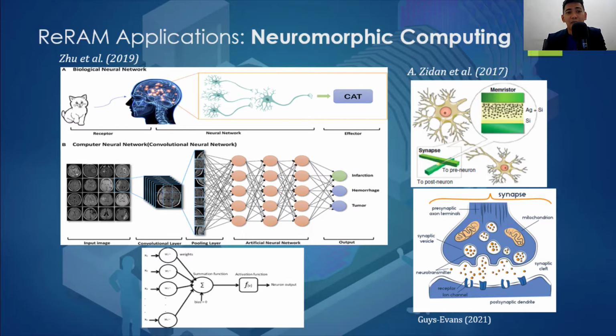But right now, what we want to know is why use memristors? Well, compared to CMOS-based neuromorphic computing or CMOS-based neuromorphic networks, neuromorphic computing based on a ReRAM array has the advantage in terms of on-chip weight storage and scaling up to a much larger array size.